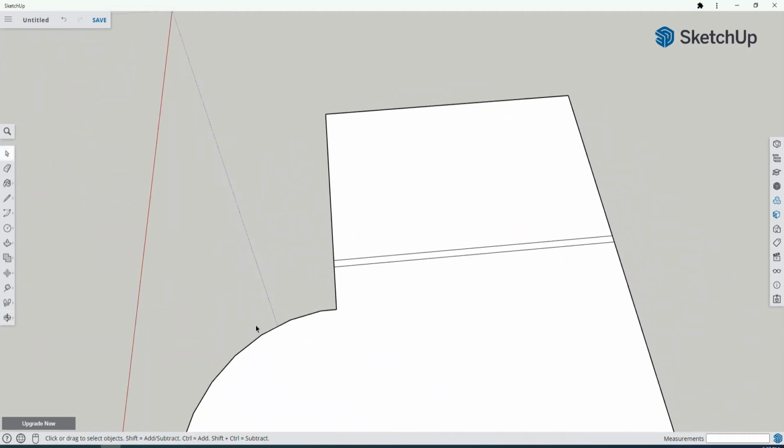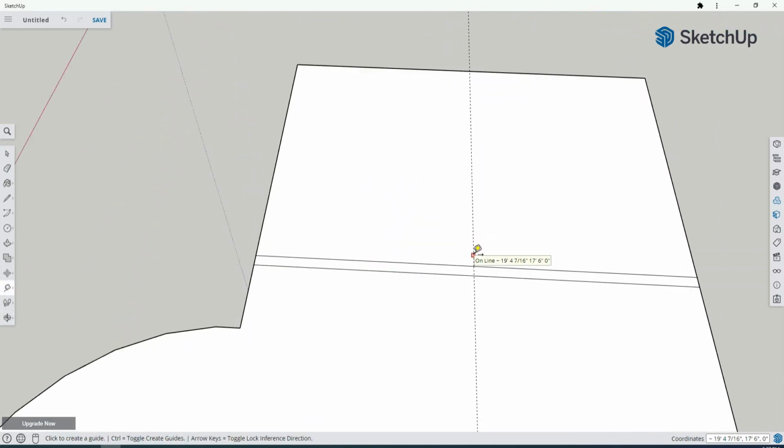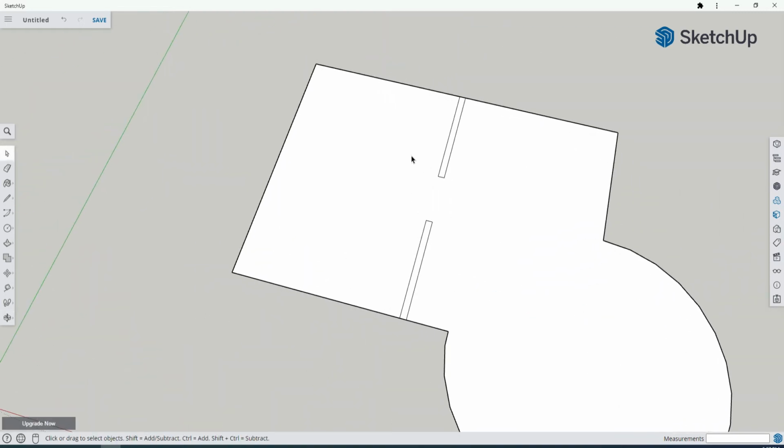Easy as that. I can do the exact same thing to cut a door, let's say right in the middle here of my wall. So grabbing the measuring tape again, go to the center. I know that doors are about 3 feet wide, so that's 1.5 feet in either direction, 1.5, 1.5. Again, going back, grabbing the line tool, slapping it on either side of that door, and then selecting and deleting anything I don't want. So that's the reference lines, and then cutting open that door there.